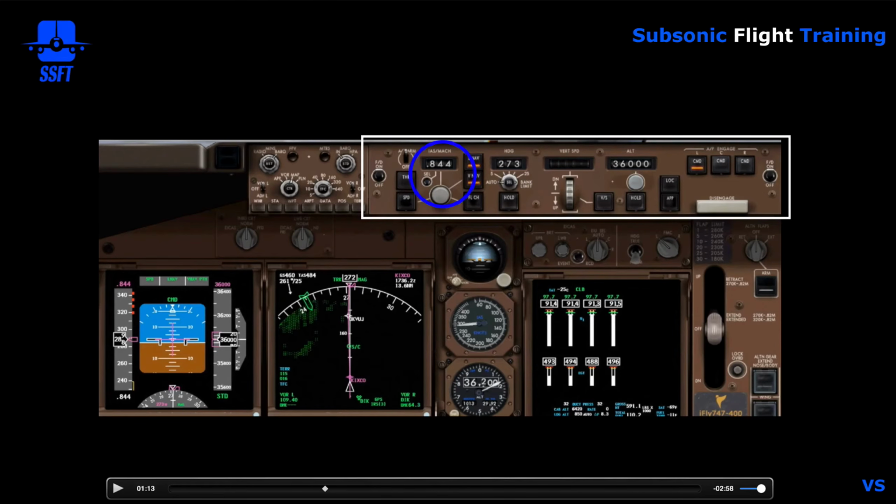So what we've done is we've opened the window and we've told the computer, I want to control the speed. You don't control the speed, Mr. Computer. If I want the computer to resume speed control automatically, then I'll push the selector again, the window will blank, and control will go back to the flight management computer.